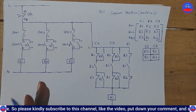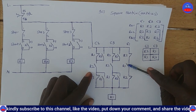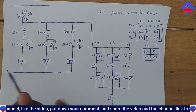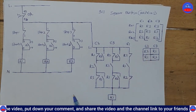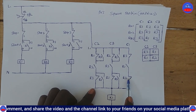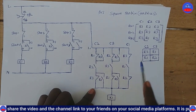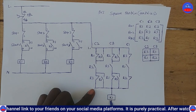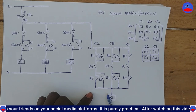Now our R1 is still energized, so it means that this side is closed. And now the contactor is energized, and our R2 is also energized. Let's see something here. It means that this side is going to open, right? It is going to open. When it opens, we have a close, close, open. So it means that this contactor will de-energize.